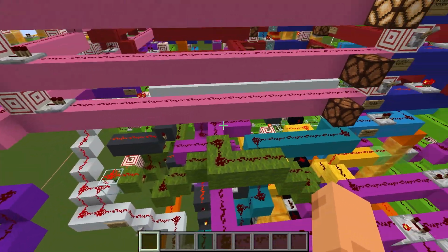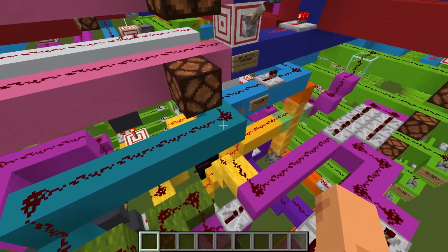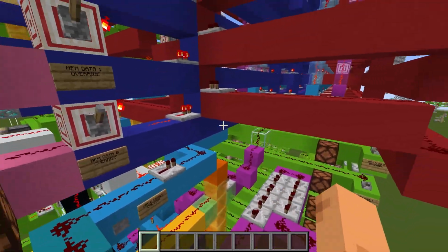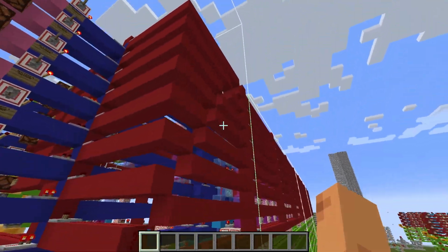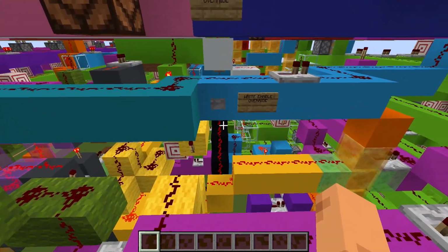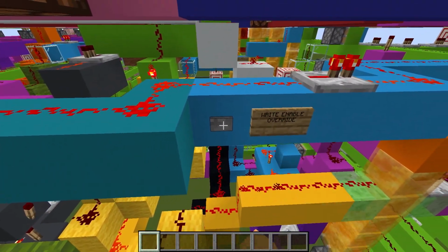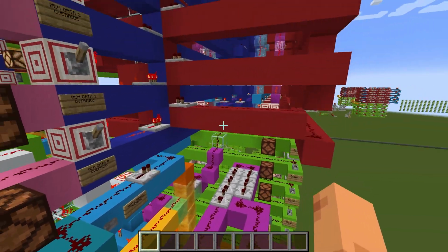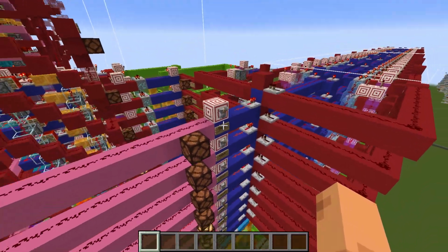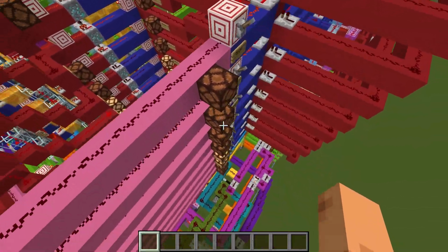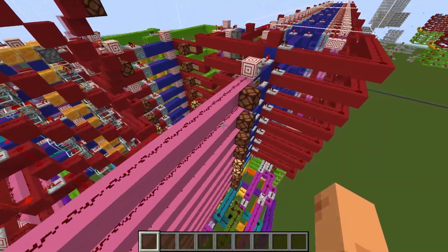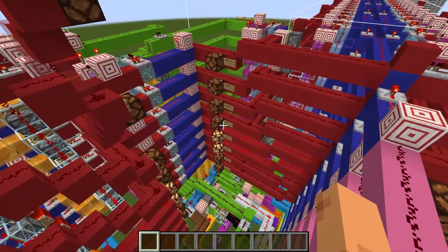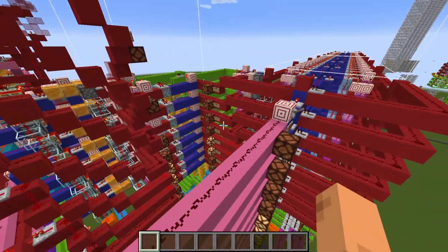Typically this signal line comes in and enables the write when we do a store instruction. In this mode we can override it, and that will propagate all the signals to write our input override value, 12, into the memory. So there we go, we got our 12 at memory location 0.